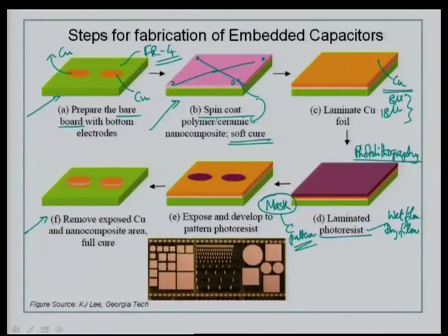What you have seen here in the picture is typical as a result of this process of using PWB methodology, photolithography, using FR4 substrate and a simple mask containing the capacitor patterns used for patterning your top and bottom plates of the capacitor.